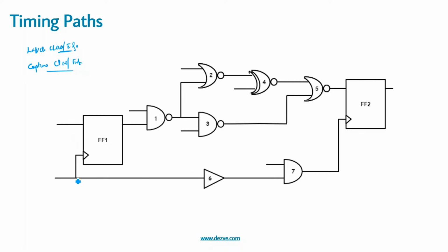So in this circuit we can see this particular clock port, this is the clock, it comes here, and this gets divided into two parts, the clock path and this path. So there is the delay of the common segment, then the delay from here to here, then the clock to Q delay, and then the delay from this point to this point, which is our data path delay.